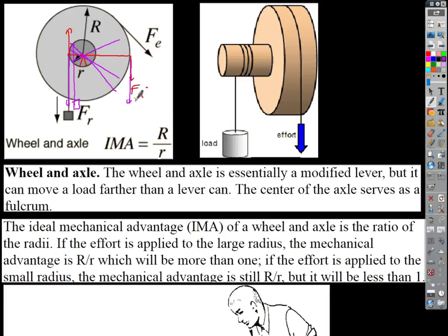And as you turn this thing, it's going to pull one of the two cables that's going to offset the rudder either to the left or the right. It's just that, right? But you've got to pull pretty hard because you've got to overcome the friction in the lines. There's a lot of water pressure against that rudder when you're going pretty fast. And so that's why you have a big steering wheel, right? And there's probably also some power steering and hydraulics going on too.